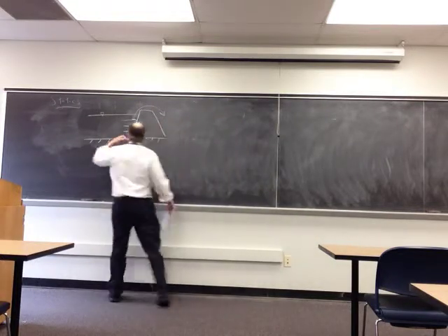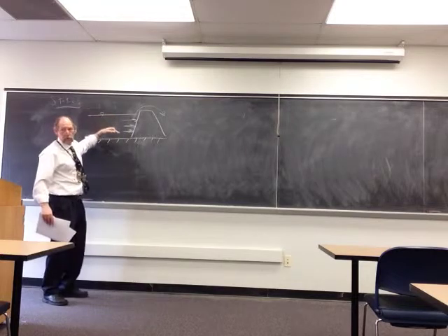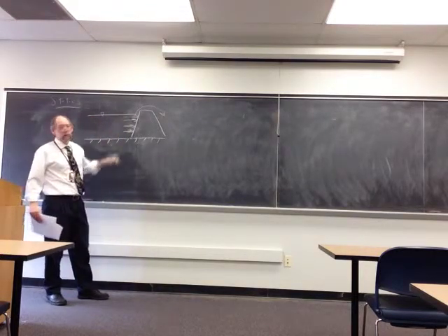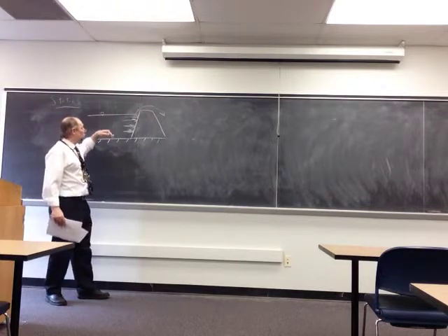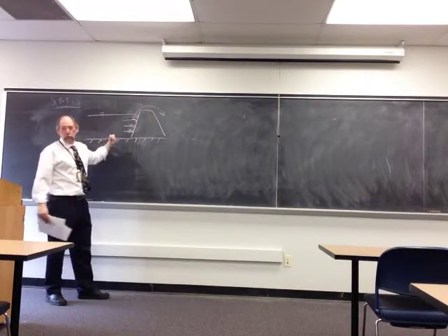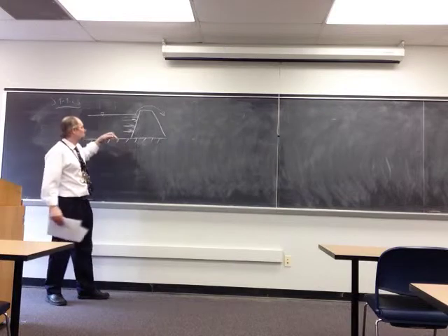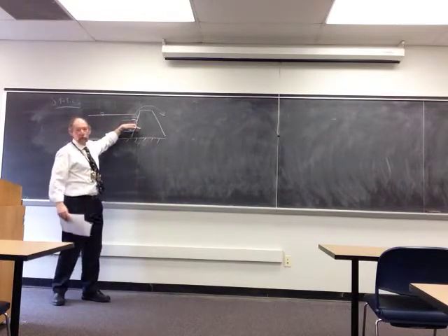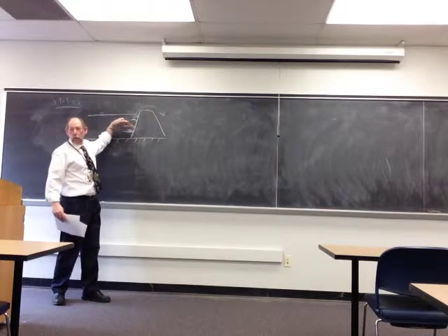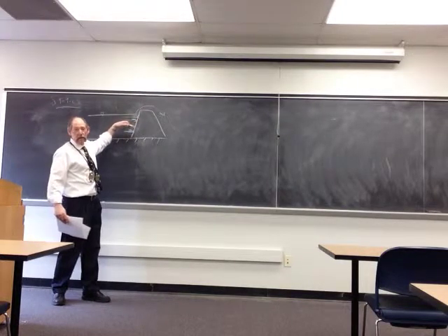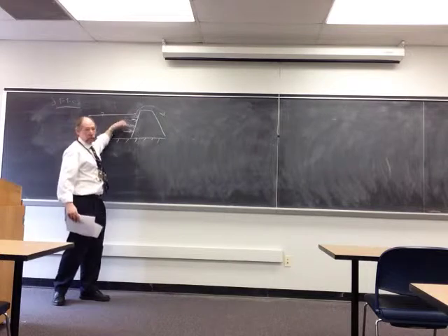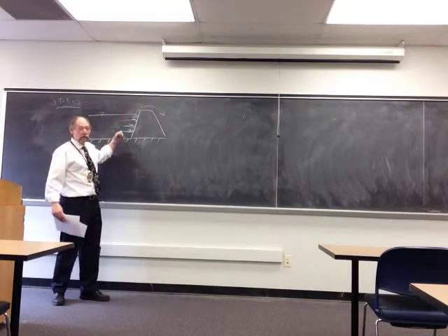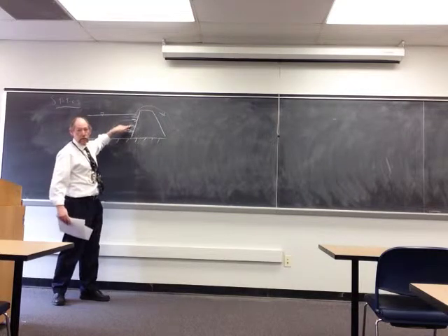So you could try to evaluate this system with a force that's acting over the entire surface. But there are engineering principles that tell you that a point force applied at the center of gravity is equivalent to a distributed force applied over the entire face. So the key then is to find the center of gravity here.